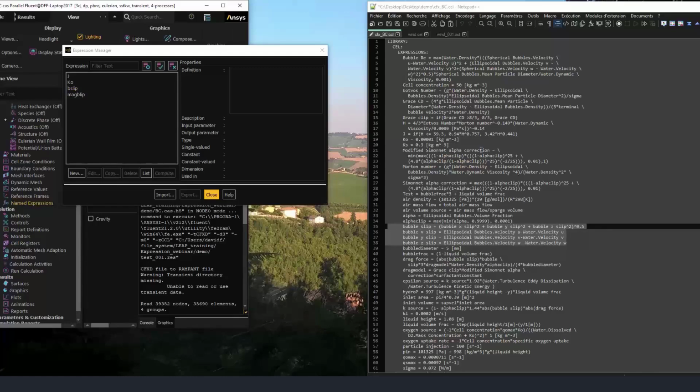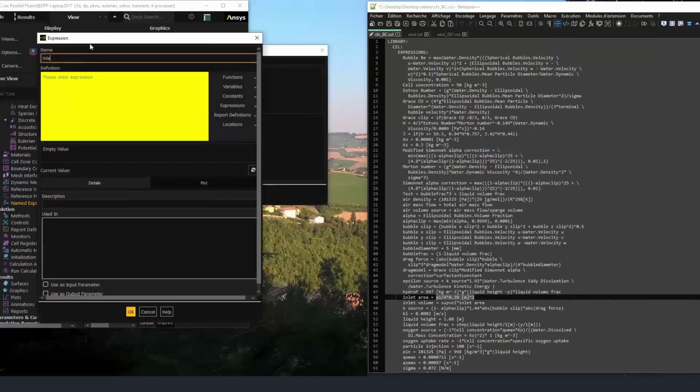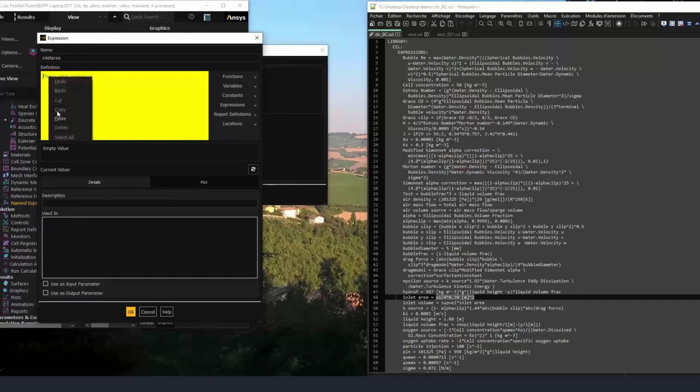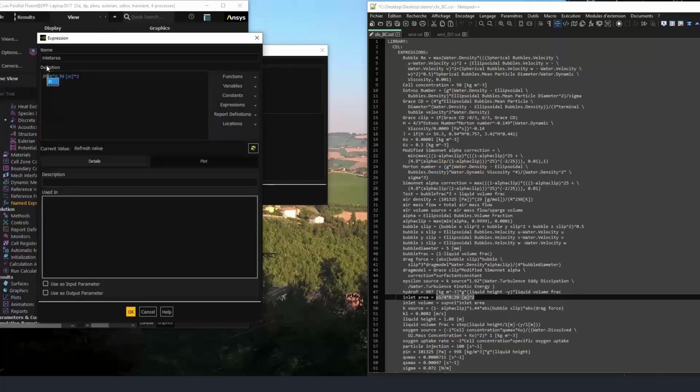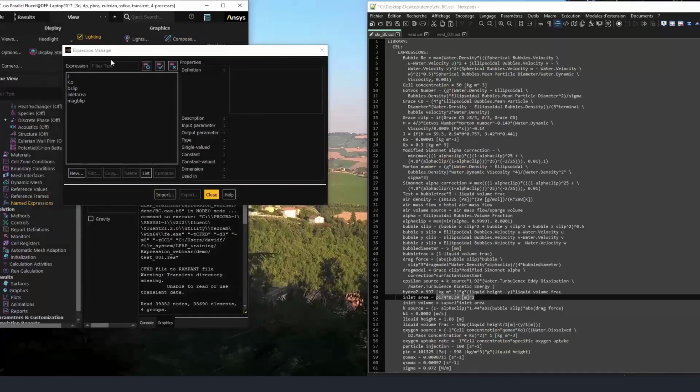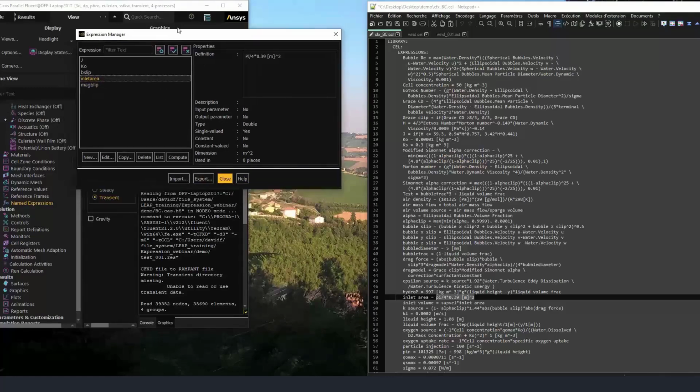Let's have a quick look at something else that might be interesting. Obviously, we would just work through doing these systematically. Yeah, look, we could do this one just to show another simple thing that needs to be done. So new, this would be inlet area of some pipe that we're not modeling. Otherwise, we would just use the area function. Pi doesn't exist. We just remember that that's there. I'd like to know how big that area is. Why can't I do that? In that area. Well, I can evaluate things once I've initialized.